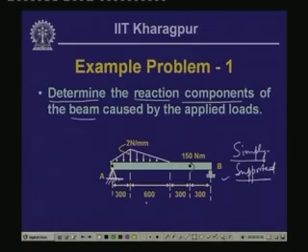The lengths 600, 300, these are all in millimeters. So, over this particular length of 900 millimeter, from 0 it goes to 2 Newton per millimeter, and again comes back to 0. And at this particular point it is subjected to a constant moment of 150 Newton meter, which we have designated as a concentrated moment.